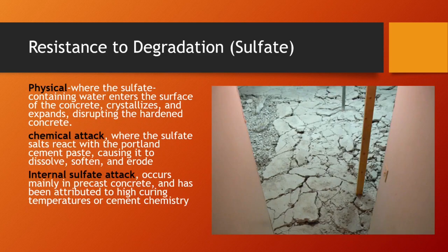Now, when we actually use materials such as stone, cement, sand, these materials are often imported from other countries, and unless these materials conform to British Standard BS or Euro Norm Codes EN, then the quality is compromised. And as a result of the quality being compromised, along with that material comes certain chemicals that are going to attack the concrete from within.